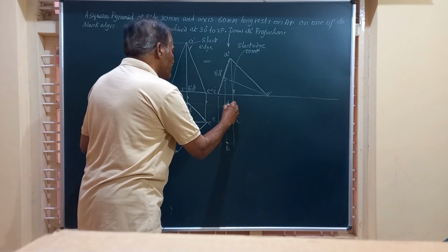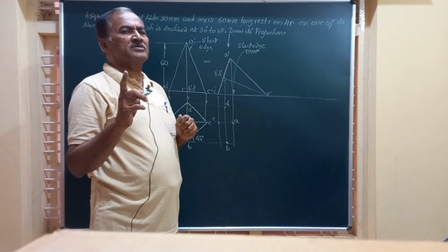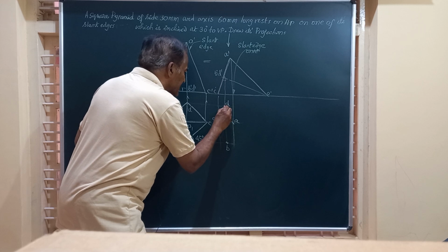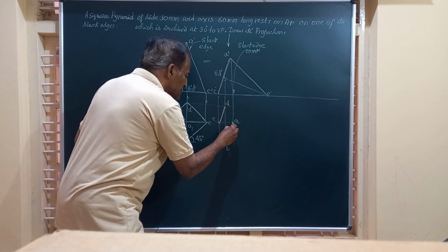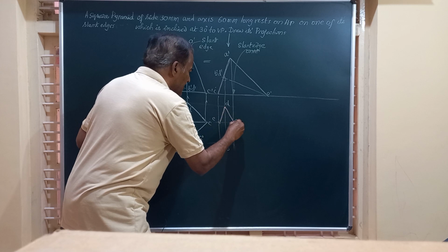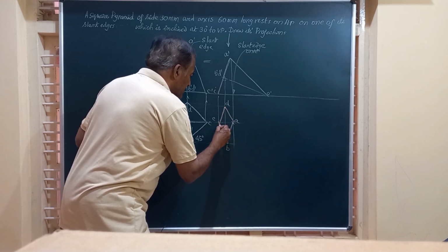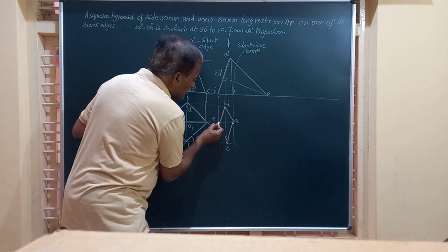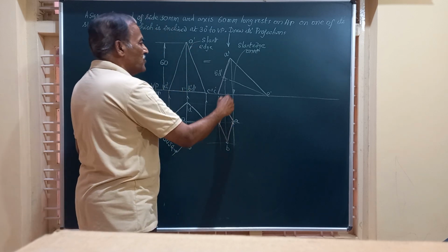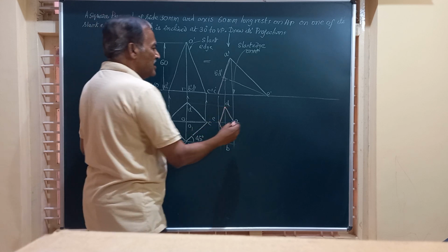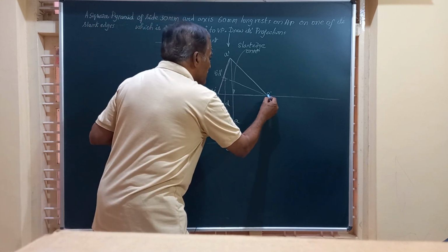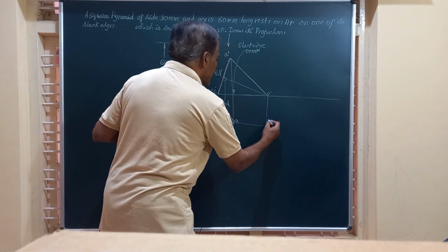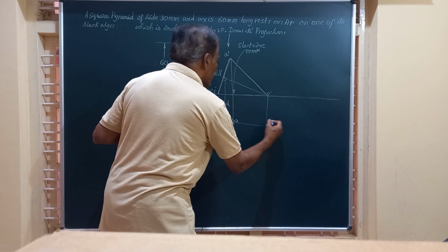And as I said before, this is completely visible in the top view. Hence, I am going to join all these by straight lines. So, this is one straight line parallel to that. Another edge, this edge is parallel to the opposite side. This is how, friends, we obtain the top view of the base, that is ABCD, and then the vertex we will draw. Draw a vertical line from O, and a horizontal line from here. The point of intersection will give you O.